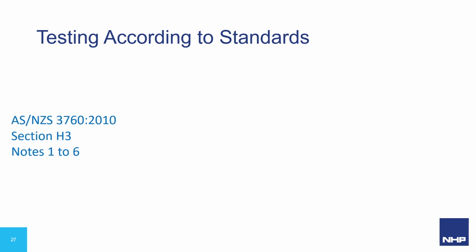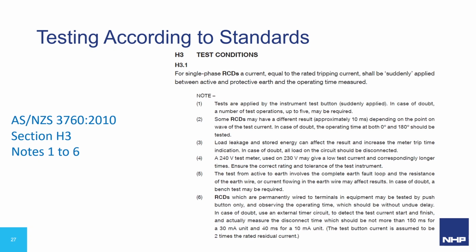AS/NZS 3760-2010, which is In-Service Safety Inspection and Testing of Electrical Equipment, specifies the testing procedures required when mandated by any body or authority. Most of the testing that's mandated is by way of workplace safety authorities in each of our regions. Section H3, Test Conditions, outlined the accepted methods and lookouts when testing RCDs.